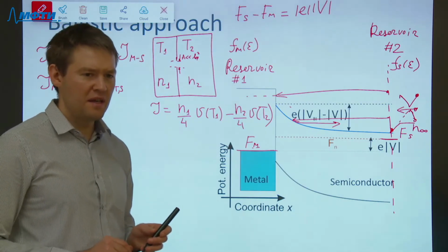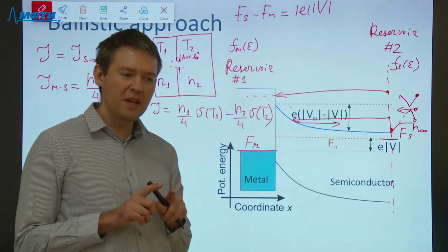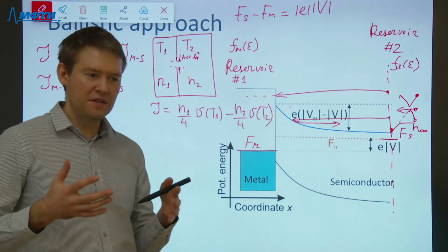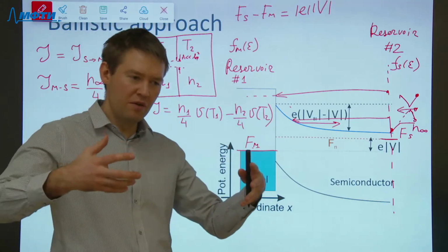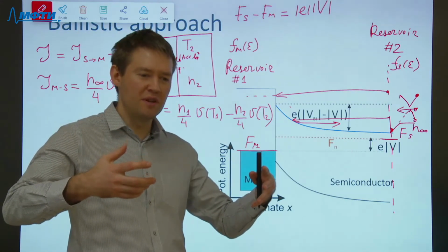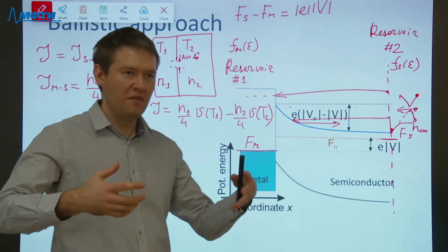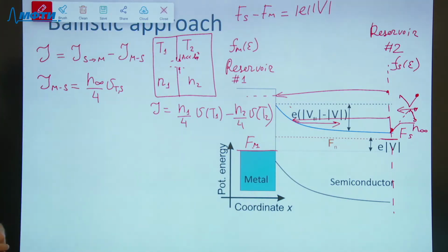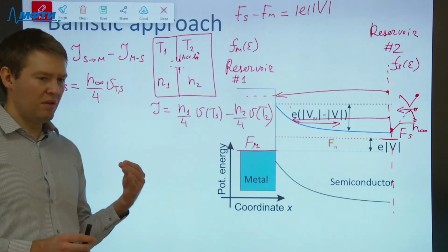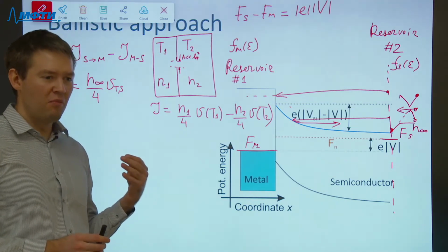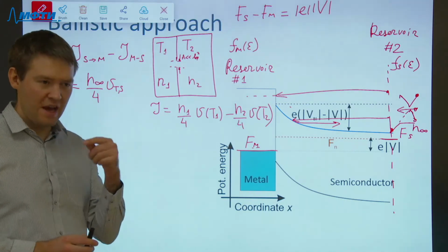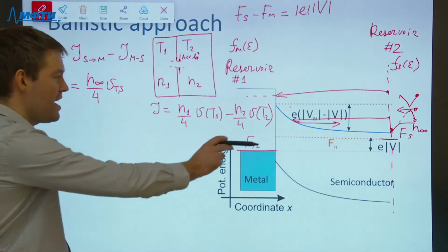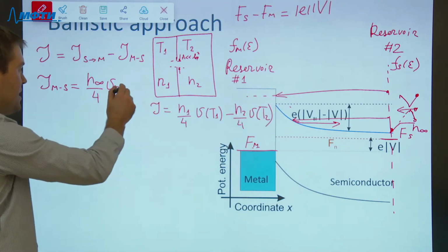It is a good suggestion for the intermediate calculations, when further the velocities have to be integrated over the Boltzmann distribution. And in the final result, we will get that only a small fraction of molecules, or actually of electrons in our Schottky barrier, would be able to overcome this energy barrier.